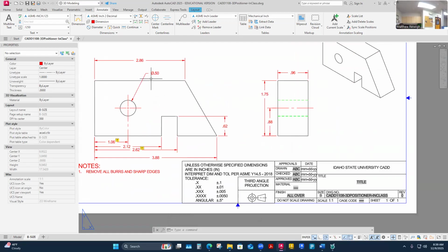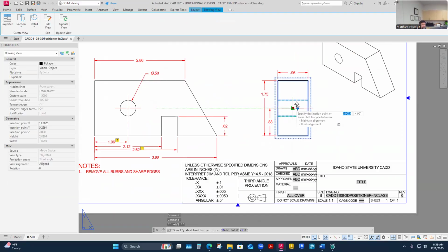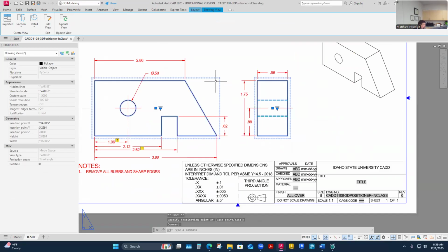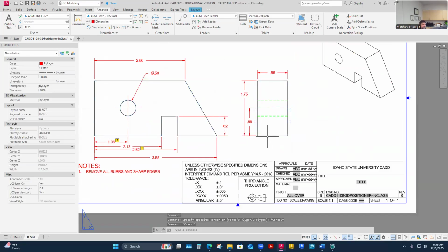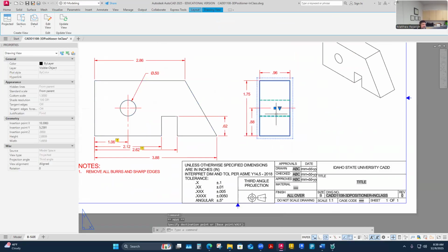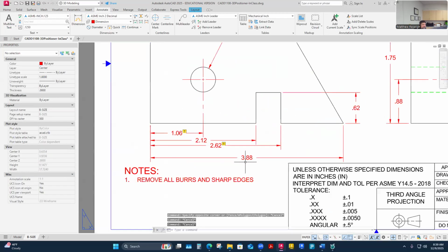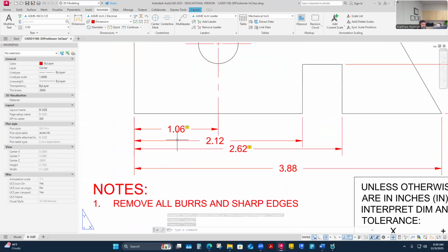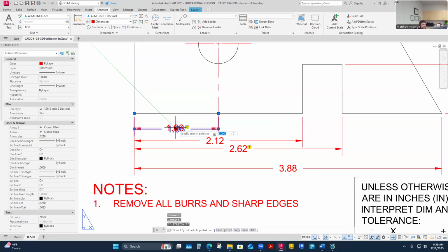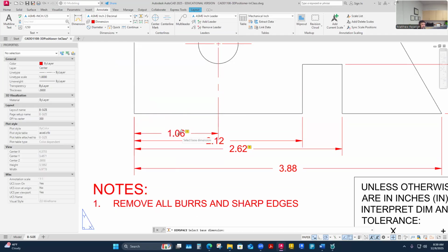If you say through here, that's fine. If we don't say through, it's understood to me. I don't overuse the word through just because it's kind of annoying to always type into my dimensions. That's why I think I'm a little lazier when it comes to that, unless I have a through all through multiple pieces. So let me get this one. Set these spacings here. You should be 1/4 inch between them, that's kind of the minimum.